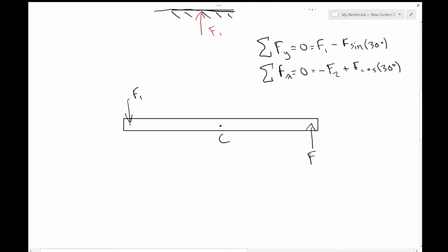And we call this sort of rotational force, if you will, a moment. So I'll draw that in here. We're going to draw our moment like this, and we know that it's going to be spinning in the anti-clockwise direction, right? Because F is going to come here and push it that way, and F1 is going to come here and push it that way. And so this whole object is going to start to spin around its center of mass. It's not going to translate anywhere. It's not going to move because F1 and F are balanced, but it's going to start to spin.